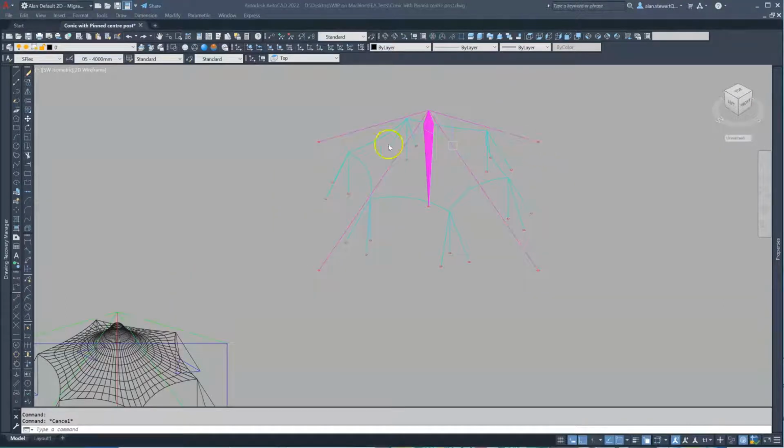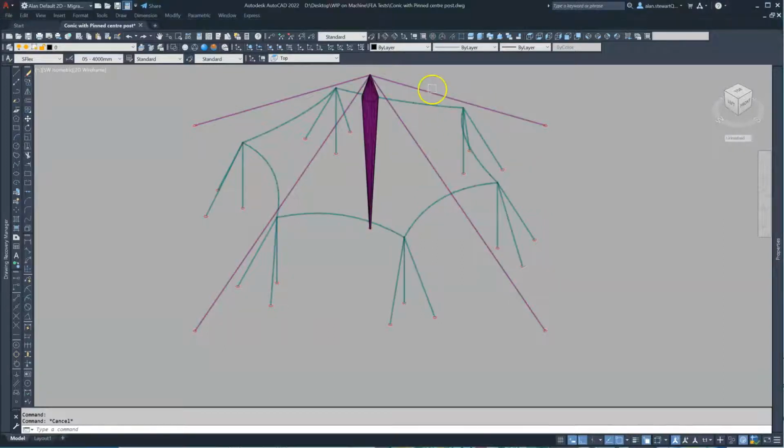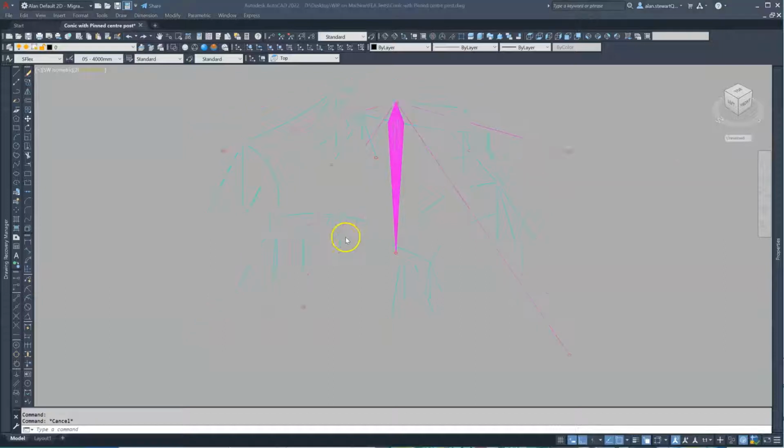When we plot the model restraints and the cables and guys from the Check Model tab, we see all of the cyan elements. The initial tensions are automatically calculated by the FEA software, and the magenta elements the software cannot calculate, so we need to manually establish initial tensions for these cables.